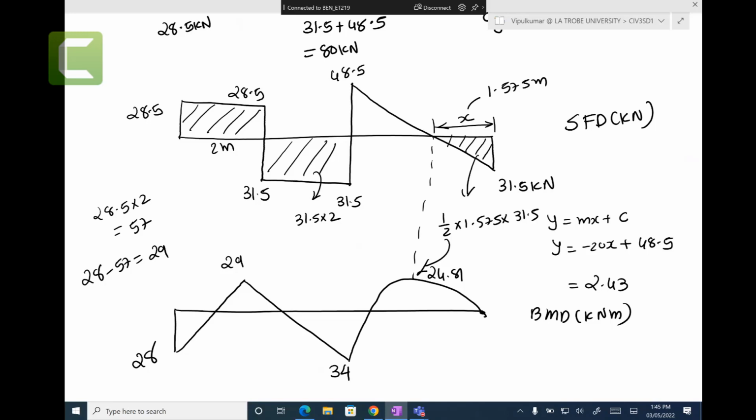The numbers Space Gass gives for the reaction forces are very slightly different. Why is that? Because of the rounding numbers that we use in the mathematics. This is the slope deflection method; Space Gass is the stiffness method. In Week 11, we will teach you how Space Gass does the calculation behind the screen. But the slight difference comes from two reasons: rounding errors from our calculations, where we take 2 decimal places, 3 decimal places, and the slope deflection method itself.